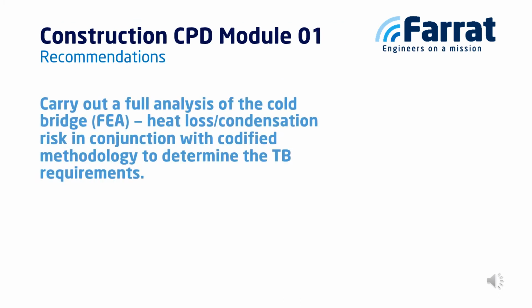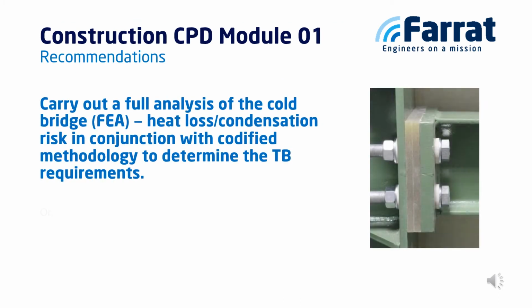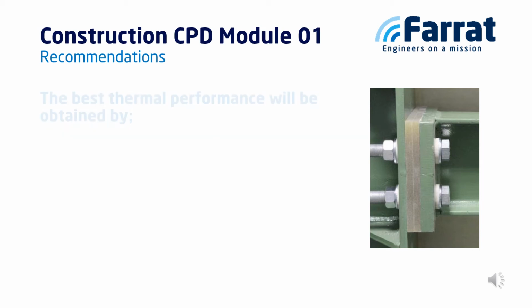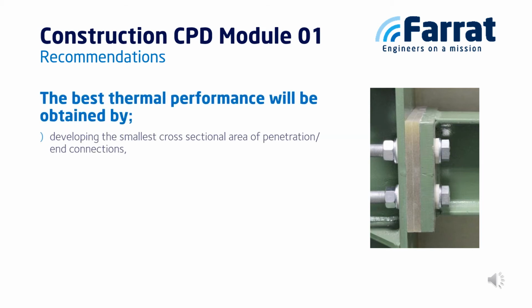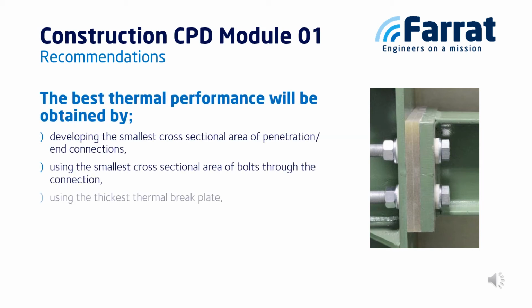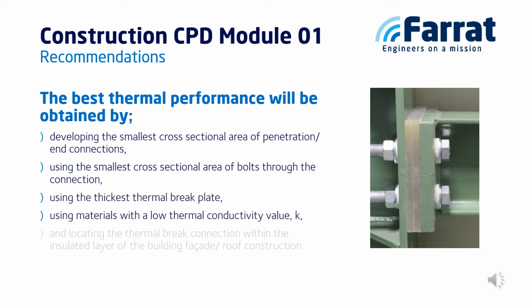After determining the thermal performance of the construction detail, either through FEA modelling or using the exemplar details for the smallest cross-sectional area of penetration or connection, you should then select the thickest thermal break plate with the lowest thermal conductivity to ensure the connection achieves the optimum performance.